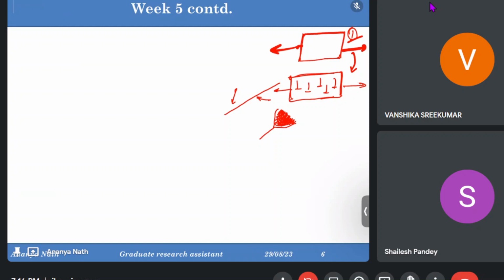So the solute atoms feel it is a preferable site to come and sit over there. But for that, the spacing between these two dislocations needs to have a certain value so that the solute can come and sit. Obviously, if it happens due to some reason, there is a stacking fault, so this is called the stacking fault.